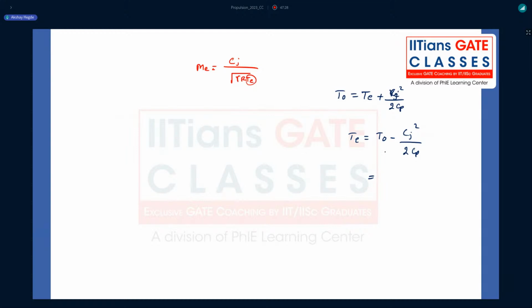Cp, what is Cp? Cp again I can calculate from the given information using the calorically perfect gas assumption, gamma R by gamma minus 1. This gives me 1005 joules per kg Kelvin, because R is 287 and gamma is given as 1.4. So from here I can calculate what is Te. So Te is nothing but 687.56 Kelvin.